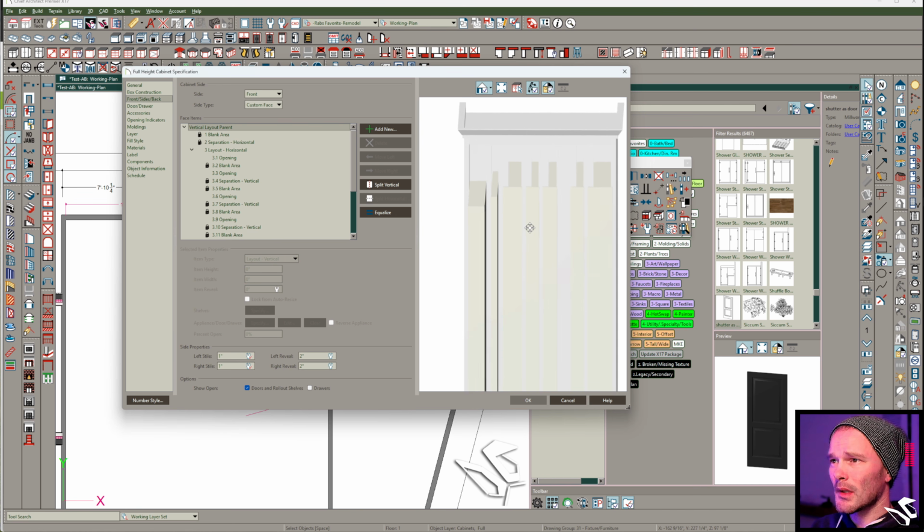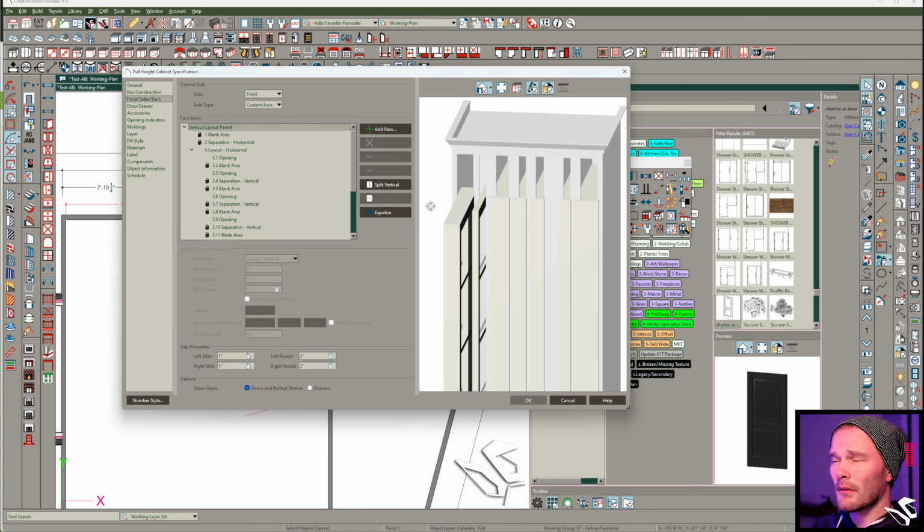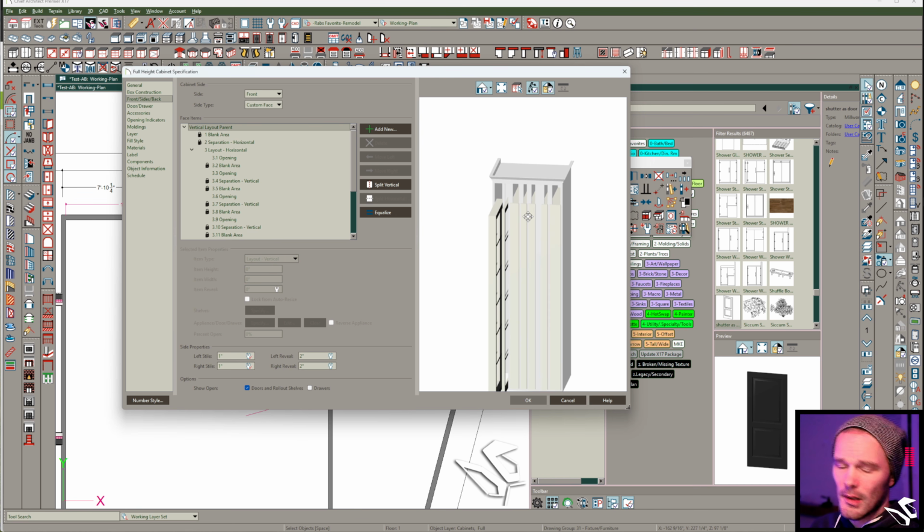I need something to break up every section in order for one of those millwork symbols not to span the whole area. Chief does something automatic when you have neighboring elements and there's nothing to break them in between. Chief's going to push that millwork shelf all the way across. So that's what was happening. It's what I kind of had a hunch about.